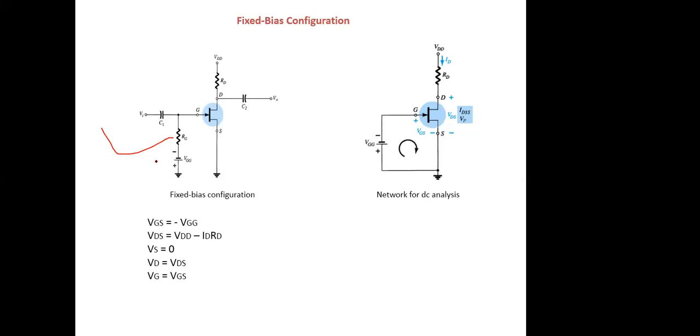In transistor also we had the fixed bias configuration. So this is a fixed bias circuit. From here you apply your input voltage, and from here you take your output voltage. This is a simple JFET. There is one resistor used with the drain, named RD. These are the coupling capacitors C1 and C2. What is the use of this coupling capacitor? This coupling capacitor is used to block whatever DC content is coming from the input.